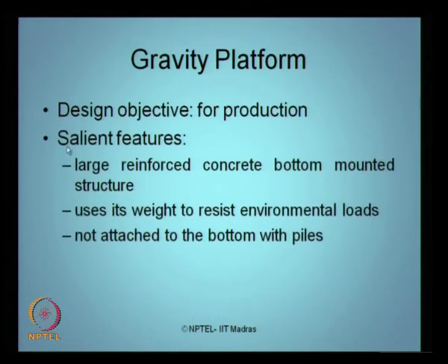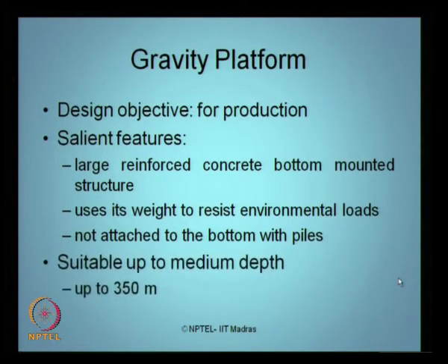If you look at the salient features of a gravity platform, they essentially consist of large reinforced concrete bottom mounted structures. Essentially these platforms use their self weight to resist the environmental loads. That is why the name gravity base platform is given to them. These platforms are not attached to the bottom through piles. They are essentially suitable up to a medium water depth of maximum 350 meters.